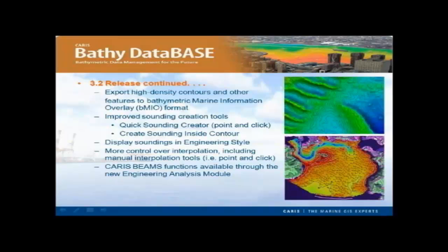So, speaking of bathymetric products, our sounding creation tools have also been improved. We've implemented a quick sounding creator, giving users the ability to create soundings using the point-and-click method, and we also have an option to create soundings inside a contour. Once the soundings have been created, we've also given users the ability to display them in an engineering style rather than the conventional IHO format.